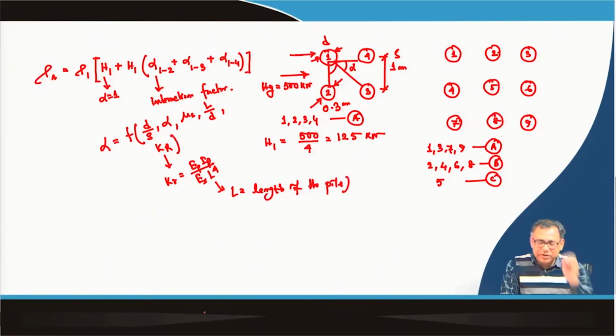So, that means this is a function of diameter and spacing, and a function of the angle, meaning the angle of that particular pile with respect to the direction of the load. It is a function of the Poisson ratio of the soil, the length and diameter of the pile, and then Kr. Kr is basically the stiffness of the pile. So, that means Ep, Ip, Es.